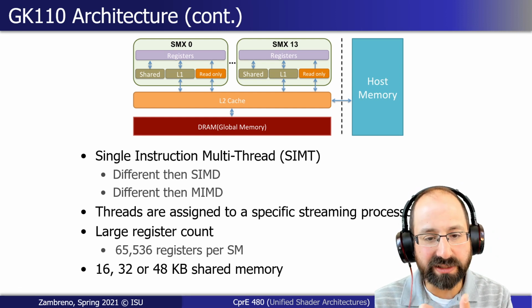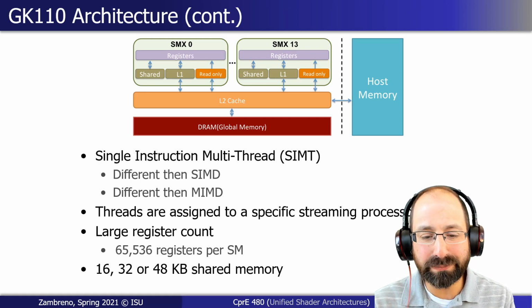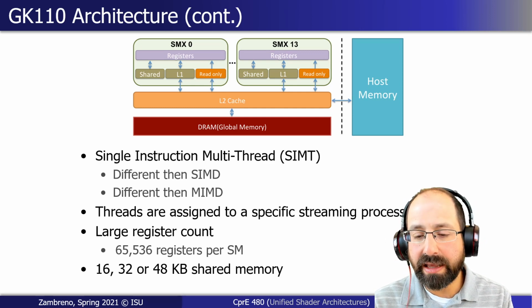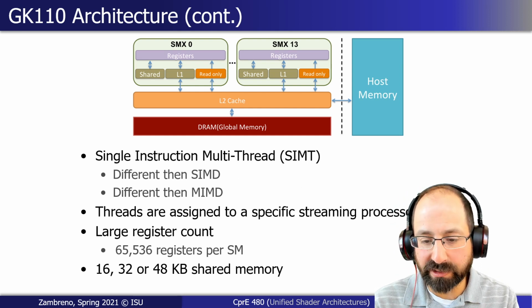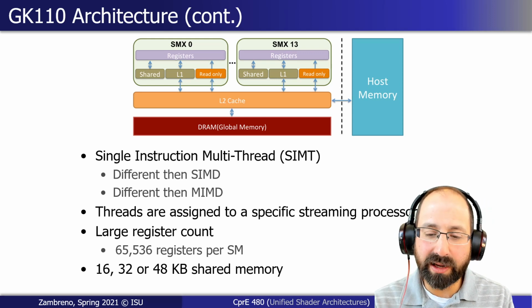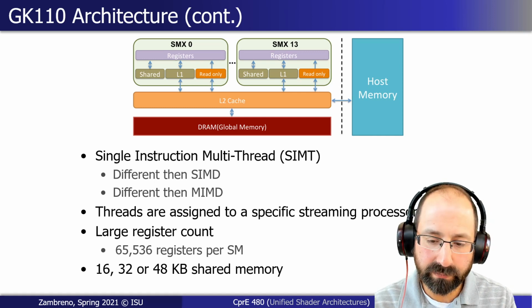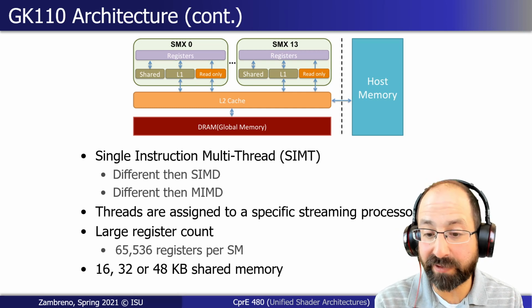And that leads to potential real savings in terms of how you do your architecture, what simplifying assumptions you can make. For example, although this has also been changing over time, in this SIMT model, you can have, say, 32 threads that are all doing that vector type of operation. And because we assume that everything is executing the same kernel, they can all share a program counter, for instance. And that leads to a significant amount of savings.